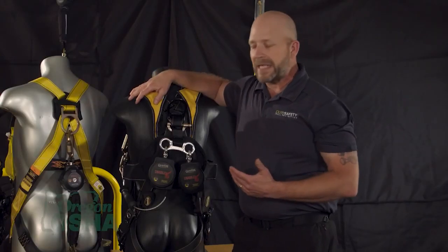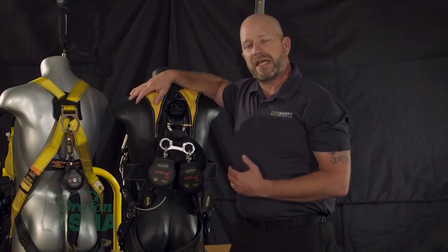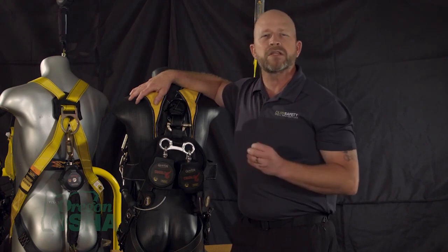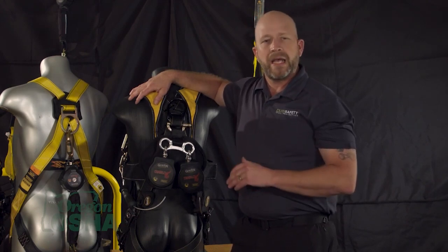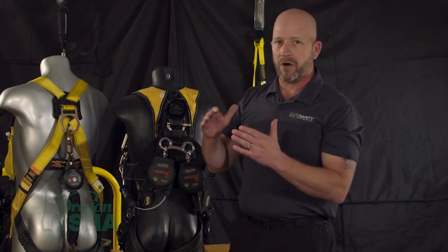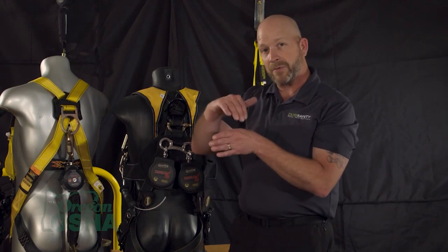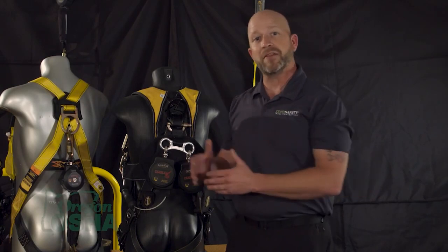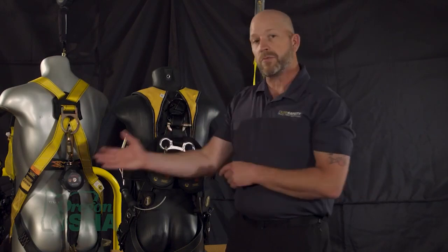There's a lot more to that; you should always investigate and assure again that we are using the right tool for the job. And just because you're working at an edge, whether it's an unprotected side edge or a leading edge, you have to concern yourselves with the fact that in the event of the fall, if the line can make contact with the edge during the progression of the fall, you must consider it a leading edge condition, thus having the right tool for the job versus one that could potentially shear.